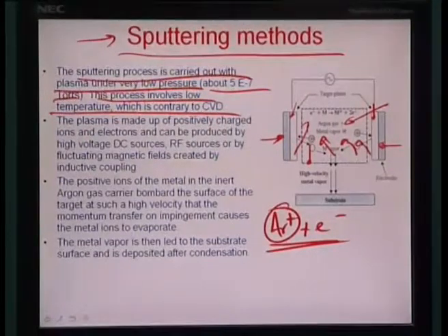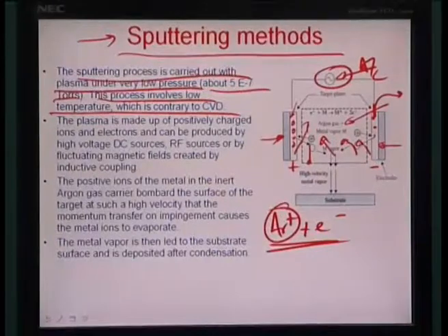The electrons and argon ions which are generated are slowly able to, if you put a bias onto the system such that this plate is made positive and this is made negative, the positive ions would hit this target and the negative electrons would hit this target. Let us suppose we drain the electrons away. So, the bias is outside here, the AC bias, okay. So, the positive plate changes from time to time if it is an AC bias. If it is a DC bias, it will only be positive on one and negative on another, but whatever happens brings a substantial amount of ionic momentum on both the plates, thus physically ablating the material off.